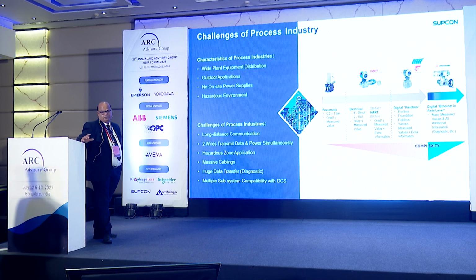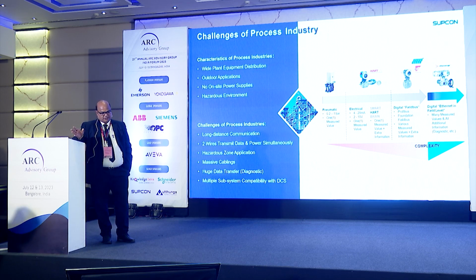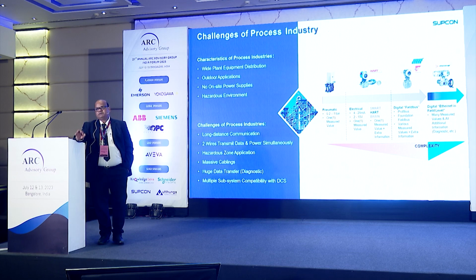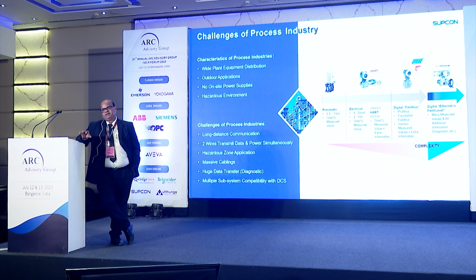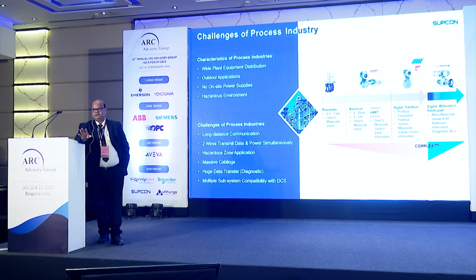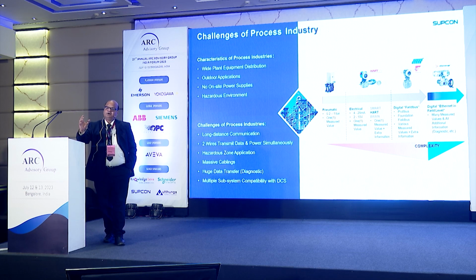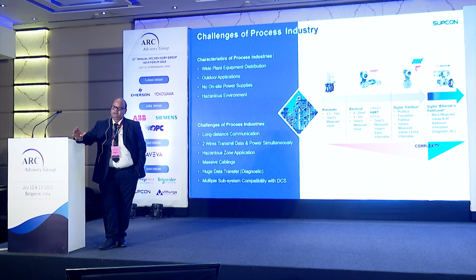So we have wide plant equipment distribution and outdoor applications with no on-site power supplies, because at -9 meter it is very difficult to work. There are also a lot of gases that we have to measure, so all the analyzers are at -9 meter, -7 meter, -6 meter at the pit, because when I store the waste for 15 days, it generates gases. To measure these gases, I majorly require analyzers.